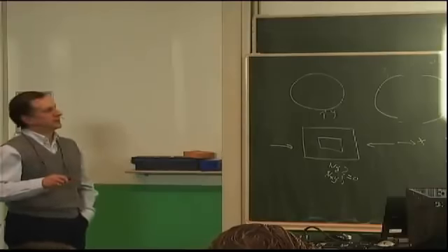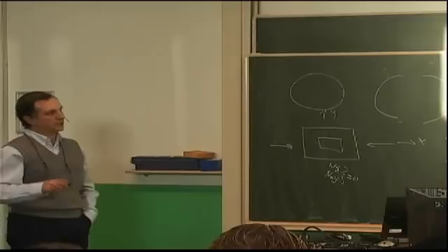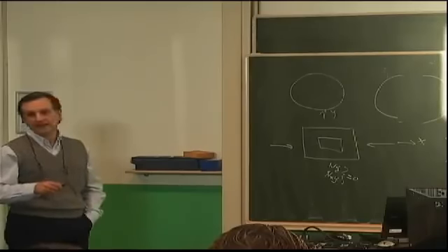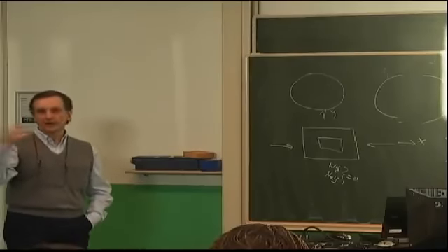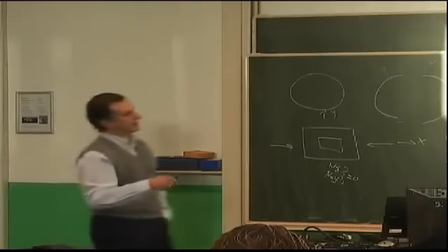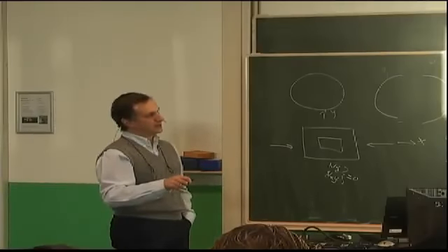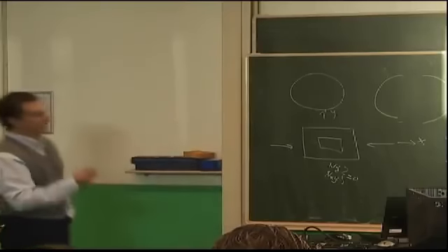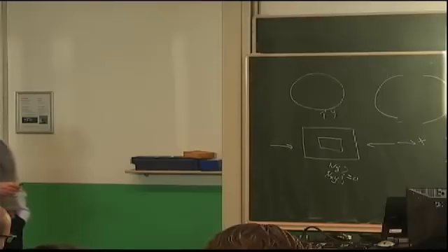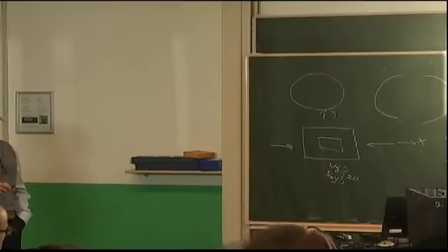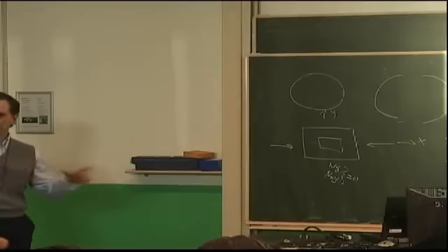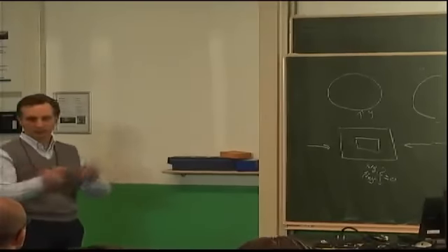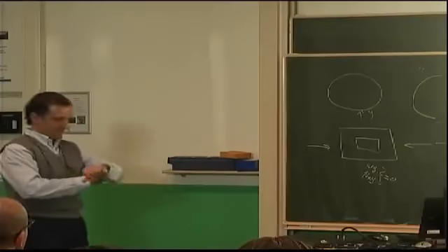This expression says my buckling will occur when N0 is equal to this quantity, which is a function of that K. So the amount of NY load obviously affects my buckling load, and the more my NY increases, this K would increase, so the buckling load would go down, for example, for a case of biaxial compression. Notice where the aspect ratio appears in all the locations, and that's significant because as I change my aspect ratio, it will change the buckling load. We'll see that in a little bit.